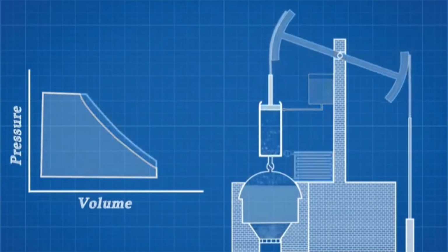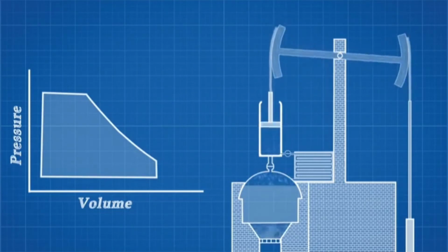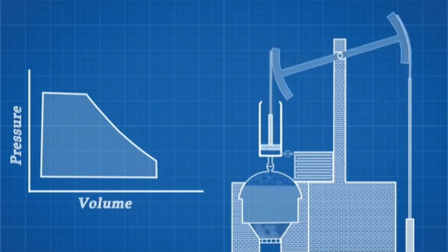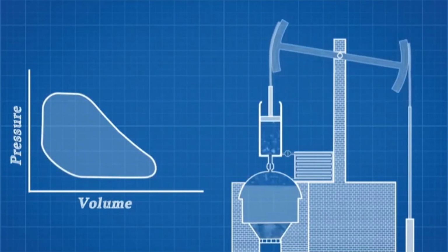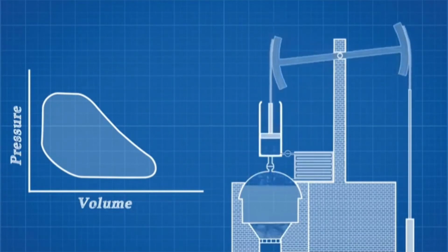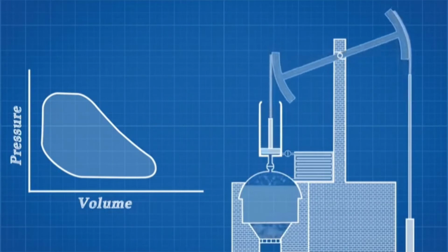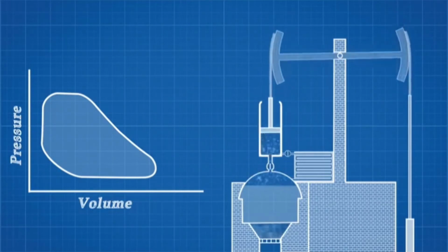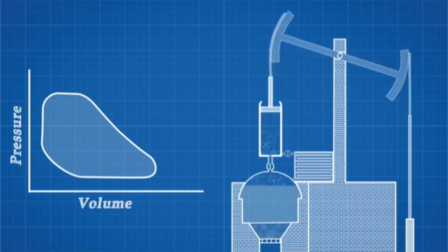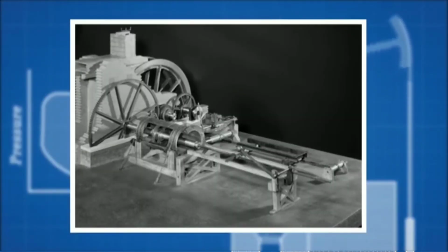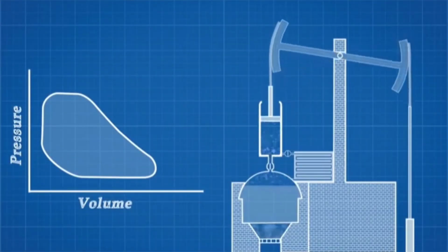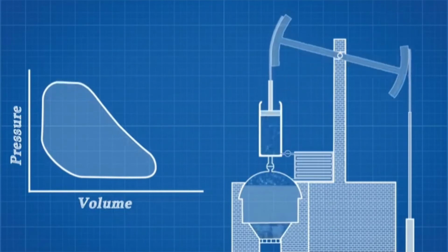So an immediate improvement is to make a separate condenser. Here the steam can be cooled without cooling the entire cylinder. There are a lot more inefficiencies involved that reduce the total work done. Many of them are unavoidable, but we can improve the situation by upgrading the piston cylinder. The manufacturing techniques needed to bore accurate and strong piston cylinders were not available in the early days of the steam engine. That changed when John Wilkinson invented this machine. This boring machine allowed for precise machining of solid iron cylinders, which reduced steam leakage and made the piston cylinder stronger, thus allowing the max pressure to rise.